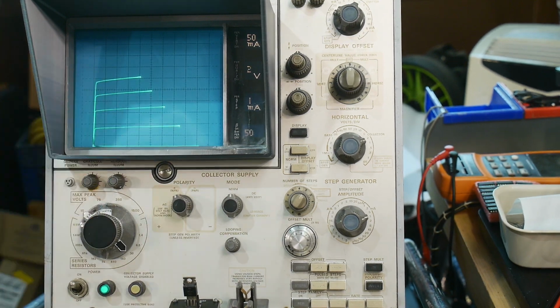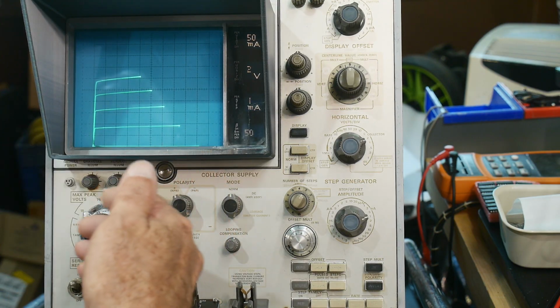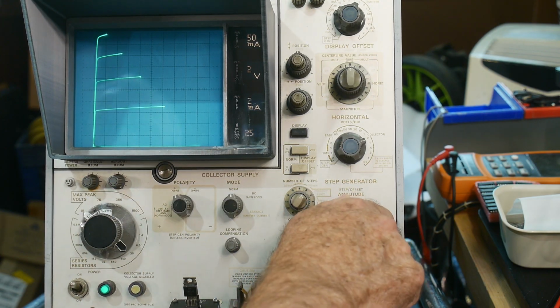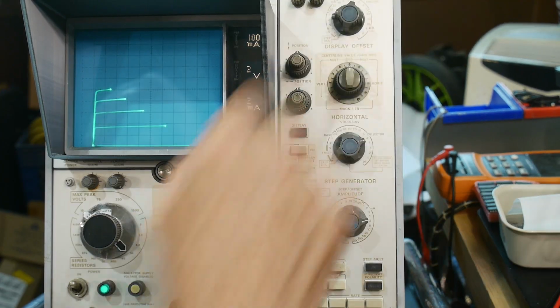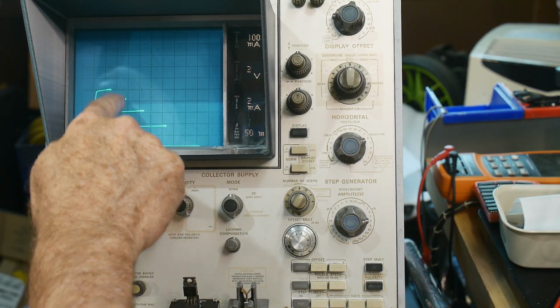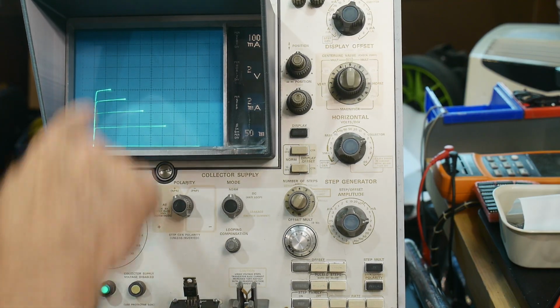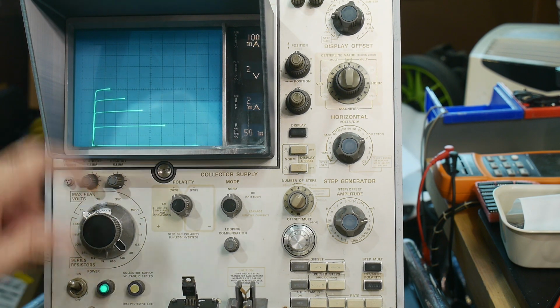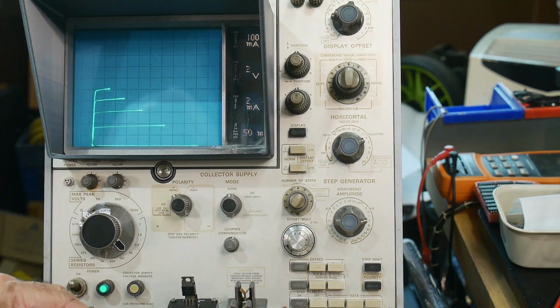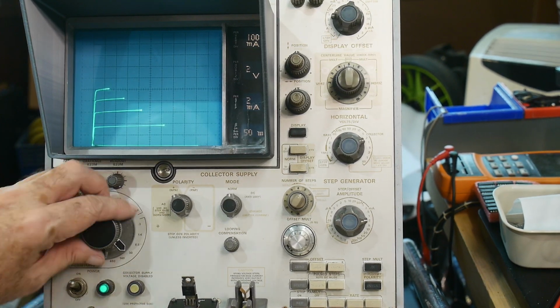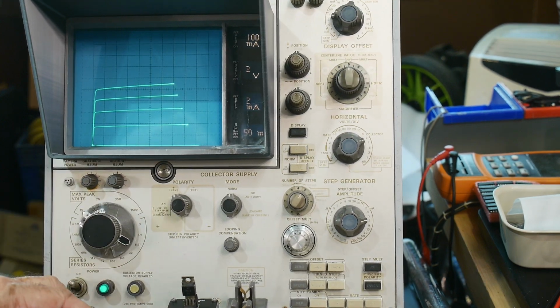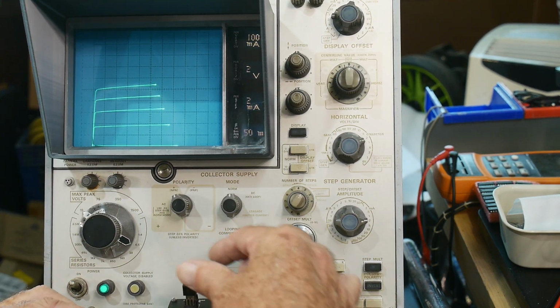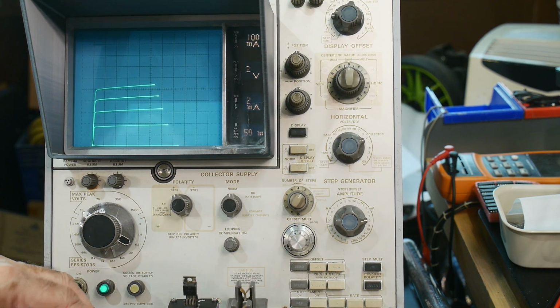If we wanted to use this transistor outputting a lot of power, we would need more base current, and we can change the amount of base current here. So let's put it here. Now we're at 100 milliamps per division: 1, 2, 3, 4, 5. So this is half an amp. We're getting half an amp of current out of this transistor here. And what collector resistor are we using? 30 ohms, okay? Here's 6.5 ohms, so 6.5 ohms. This transistor is probably getting pretty toasty now. Yeah, it's getting kind of warm.